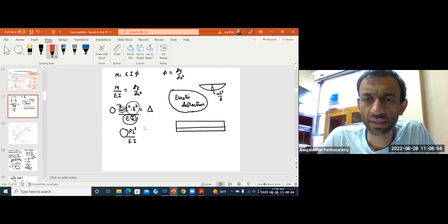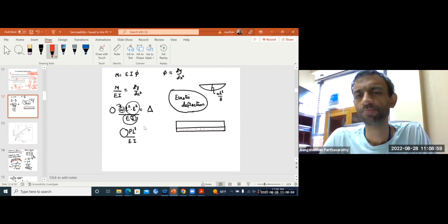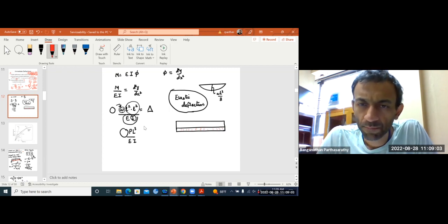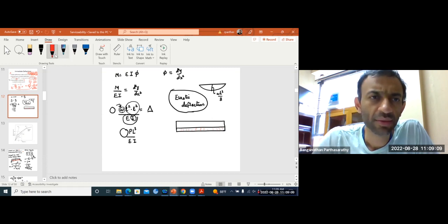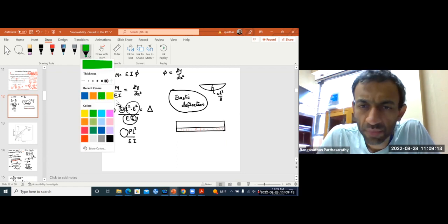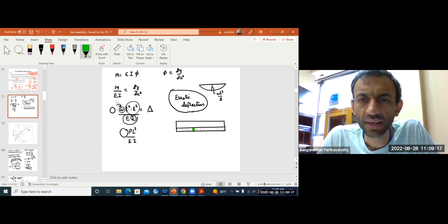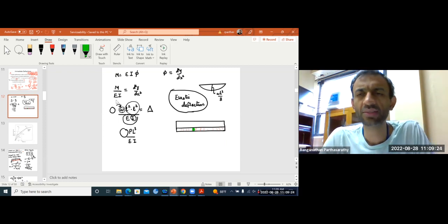Something like that, okay? So you can see in between these two cracks, your beam is uncracked, right? That means in the region between two cracks, your beam is not cracked. So some places of the region you have a cracked beam, some places you have uncracked section.